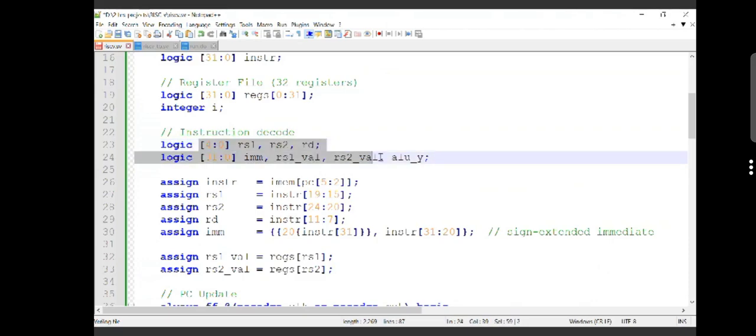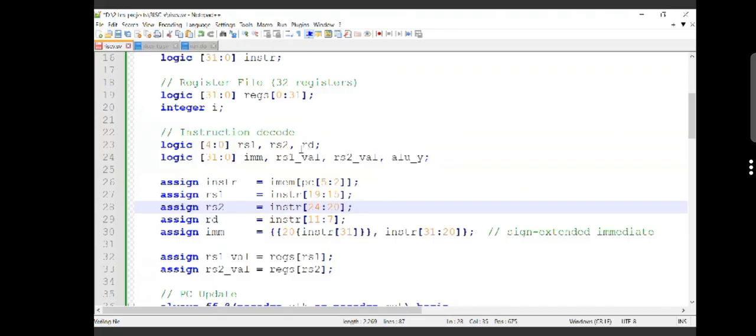Here this is the instruction decoder, where the instruction decoder will extract your fields. Here we are extracting the fields itself, where we are using the read pin. That is the destination register, meaning where you want to read from, the destination source. You are having source and destination. So RD is nothing but the destination register. RS1 and RS2 are your source registers. You are having two source registers, RS1 and RS2, and your destination register.